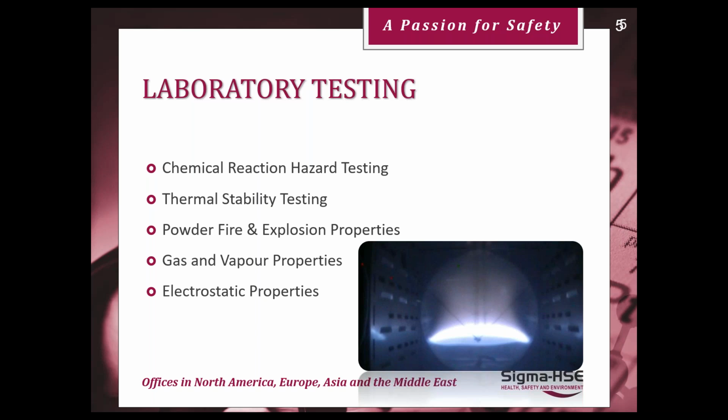And you can see that we span not just powder and gas and vapor fire and explosion properties, but also electrostatic properties, thermal stability testing, and chemical reaction hazard testing. So we've got our own Carius tubes and DSCs and various types of calorimeter to really get a good understanding of chemical reaction hazard.